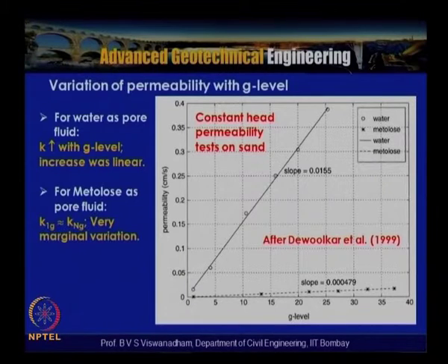We also said that when we replace the conventional pore fluid with a model pore fluid having high viscosity, the permeability will remain the same, that is Km is equal to Kp, and when Km is equal to Kp, then Vm is equal to Vp, and with that the time in model and prototype, Tm by Tp, is equal to 1 by n.